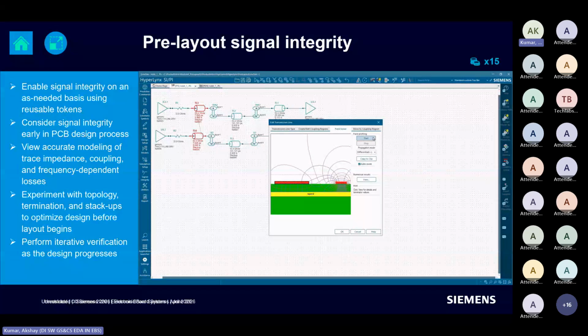have an analysis performed on the schematic, because if you simulate your schematic, only then are you confirmed that your schematic is perfectly fine. You don't need any additional resistor or termination or any RLCG parameters to make sure there is no loss between the transmitted signal and the received signal, right? So finding this kind of issue at the schematic stage helps you manage your complexity in the layout.